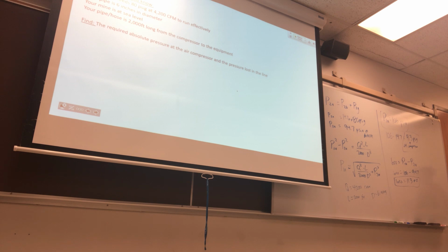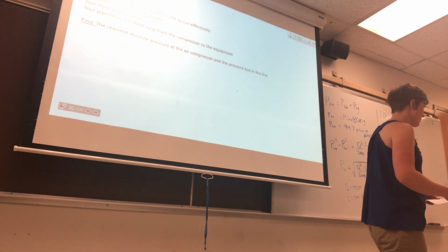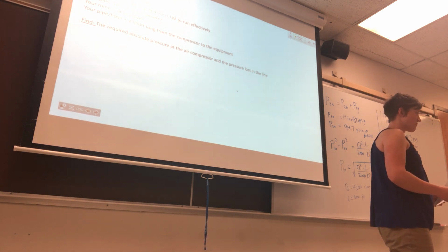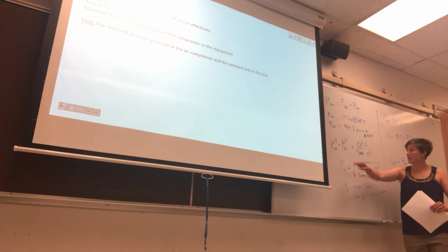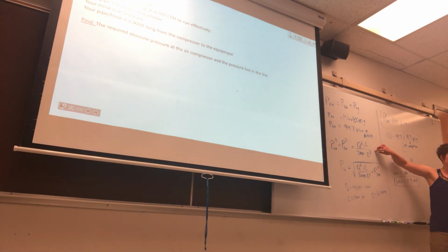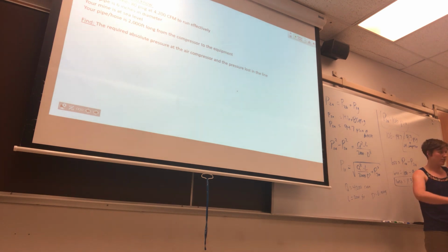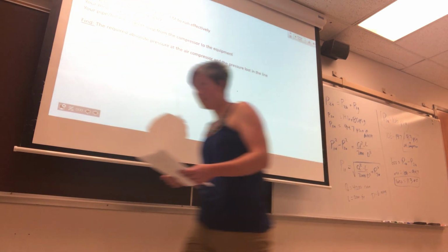Cool. What questions do you have? Line losses. Does it change based on what kind of hose you use? Like a bull hose versus a steel pipe. Yes, it does. So we use the generalized, like quick and dirty equation. But if you have something that's less friction resistant or a different material, you can use a more complicated equation for that. This is very general with laminar flow, what you'll see at the site. Yeah. Cool, good job, team.